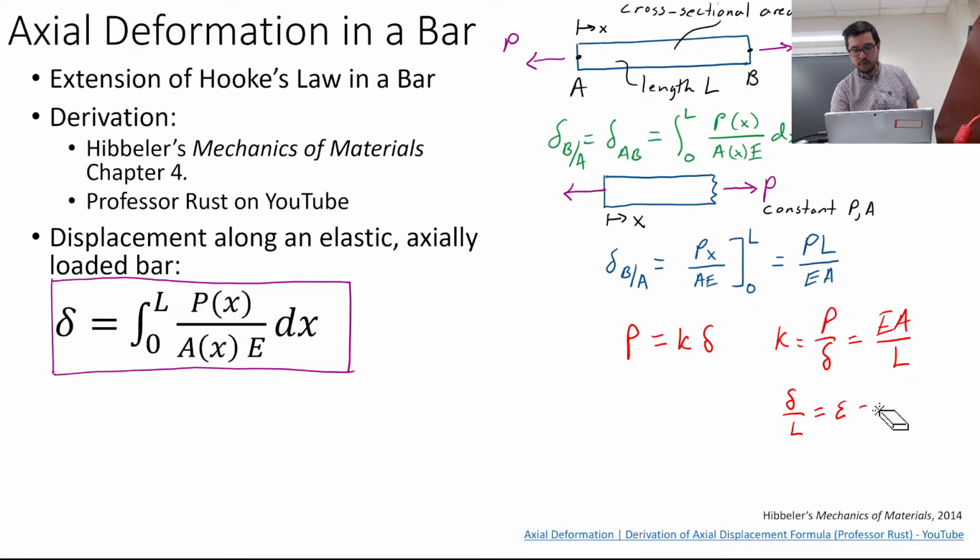Right, so, okay, or sorry. So if I do this, then I have this epsilon delta, let's do it this way. This is P over EA, right? And if I have sigma, that's P over A, right? So I can say, well, P over A, that's E. So I have epsilon is equal to sigma over E. We're just massaging equations, as some people will say.